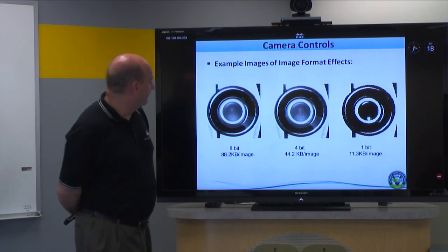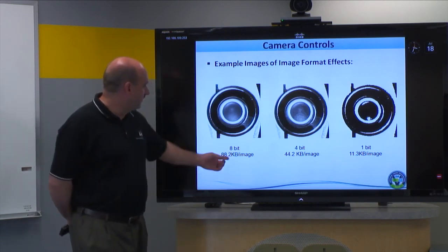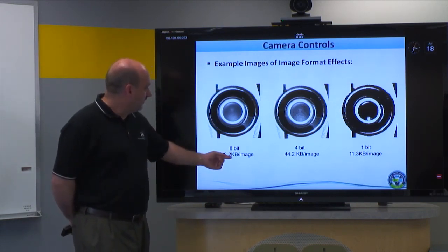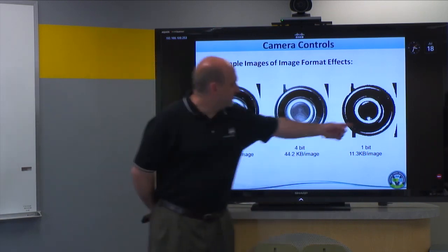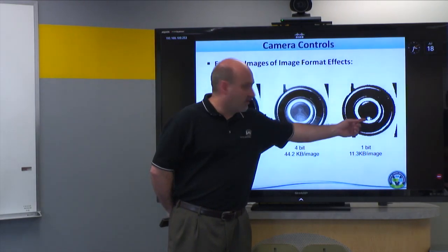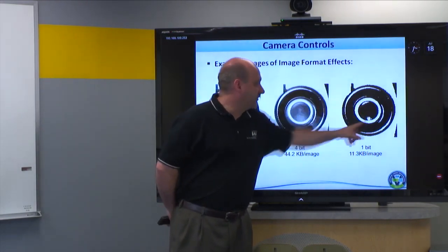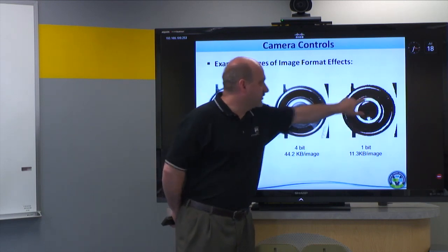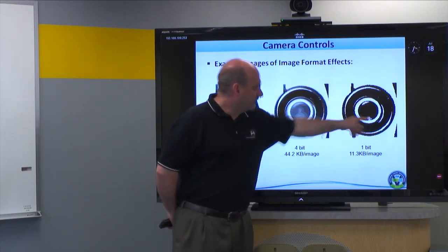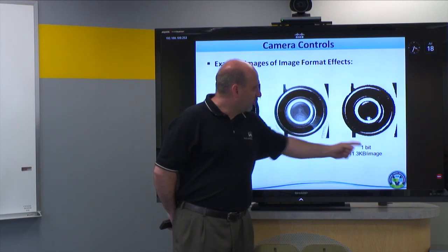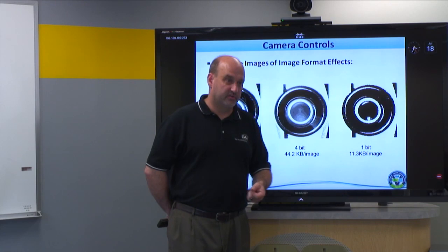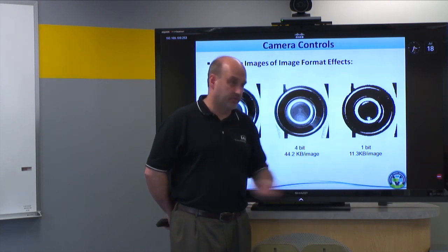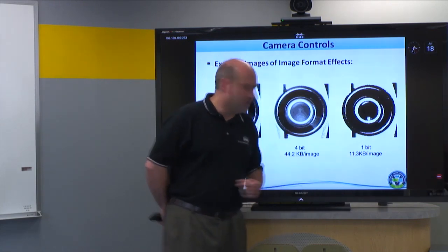So this again is more or less showing images, but it's also, notice, showing the file size associated with this image. These are all monochrome, but you notice this again is a 1-bit image, so it's all black or white, often called thresholding, to find things. If I want to measure this ring, this is maybe not bad because I can measure the edge very sharply, despite the glares. It's a 1-bit image, but only 11 kbits per image that I'm transferring. So if you multiply that times the video rate, 30 a second or something, not very much data.